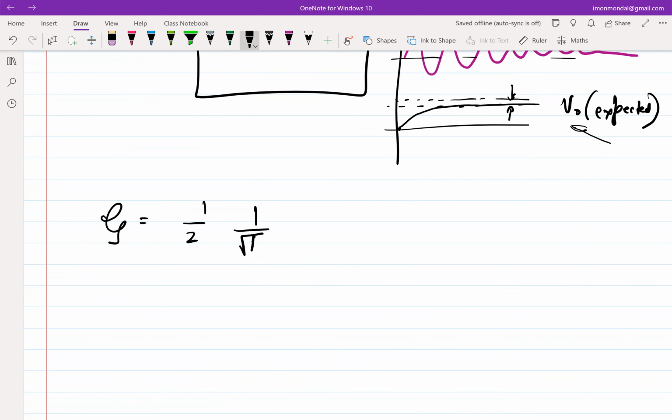The extreme case is if P2 is at infinity, which means it doesn't even exist, then it becomes a first order system. You have a single pole system, and you get all the single pole settling behavior.